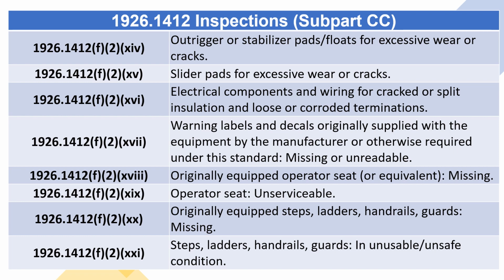Warning labels and decals originally supplied with the equipment by the manufacturer or otherwise required under this standard, missing or unreadable. Originally equipped operator seat or equivalent missing. Operator seat, unserviceable. Originally equipped steps, ladders, handrails, guards, missing. Steps, ladders, handrails, guards, in unusable or unsafe condition.